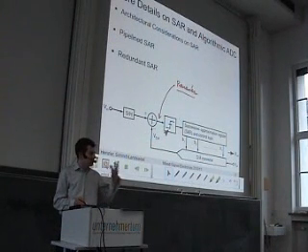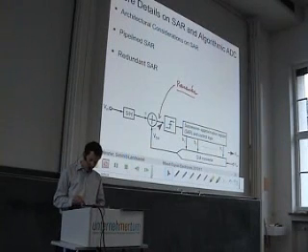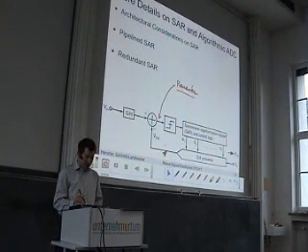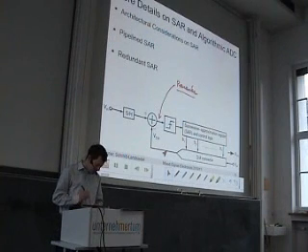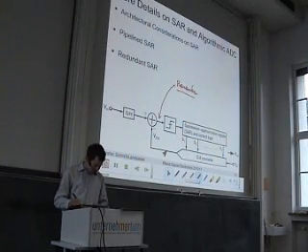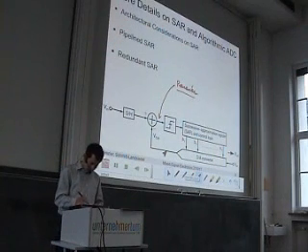The comparator says larger or smaller, or in this case we can compare against 0, and steers the successive approximation register accordingly in order to increment or decrement the DAC output. And at this node, this was what we had, the quantization error, and the goal was to make this error voltage equal to 0.